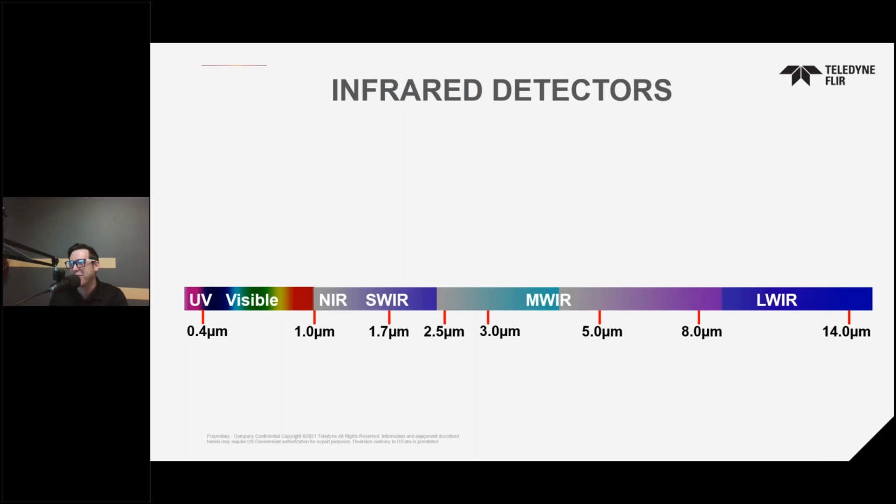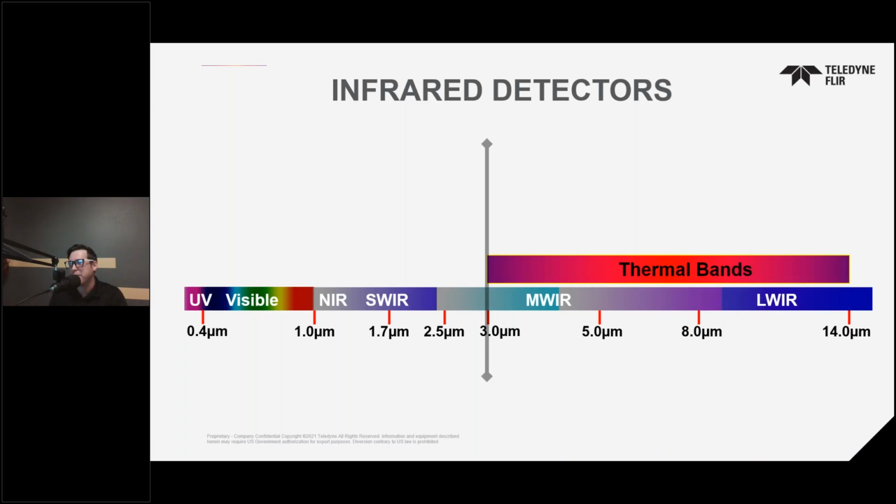The first thing to note here is where we consider the thermal bands to start. I mentioned that a second ago. This is going to be at 3 micron, and it's due in part because reflected light really dominates your signals below 3 micron, and that contributes to that SWIR camera having to start at about 400 Celsius to read those temperatures. At 3 micron and above, the mix shifts and black body radiation dominates, vastly improving the potential signal to noise ratio that we're trying to capture here.